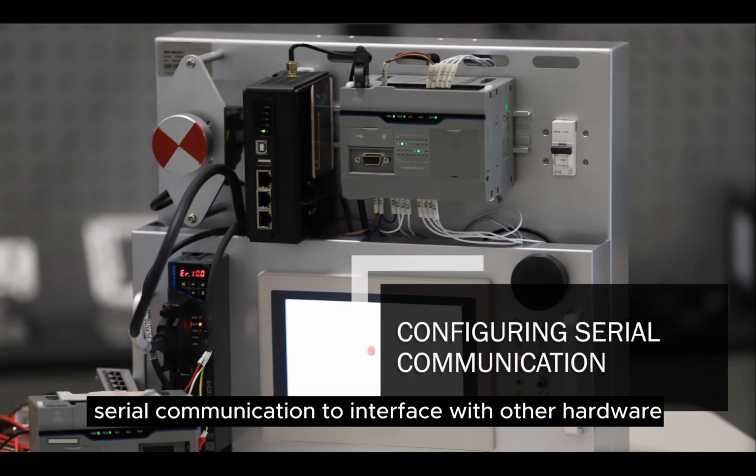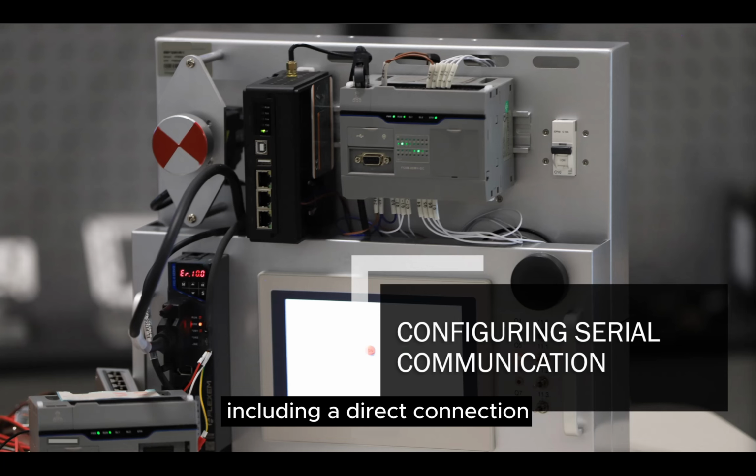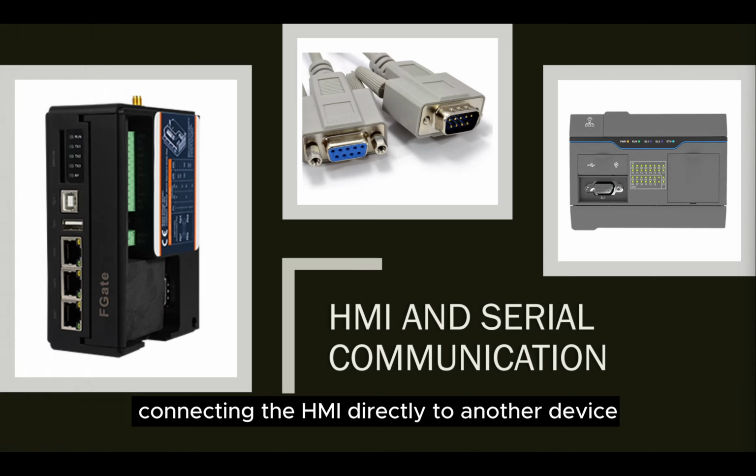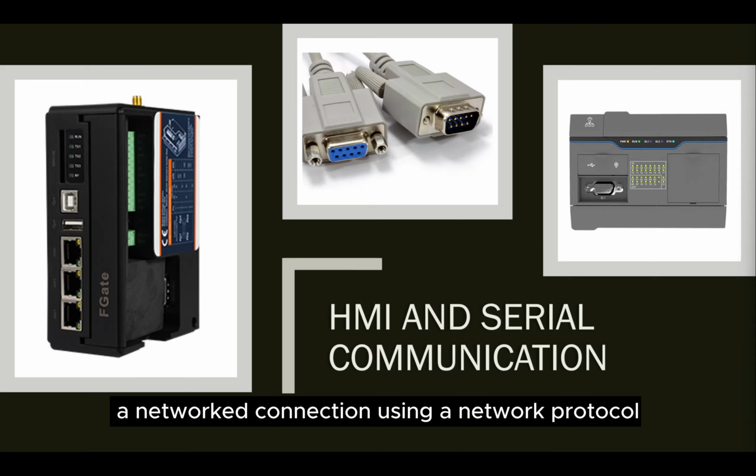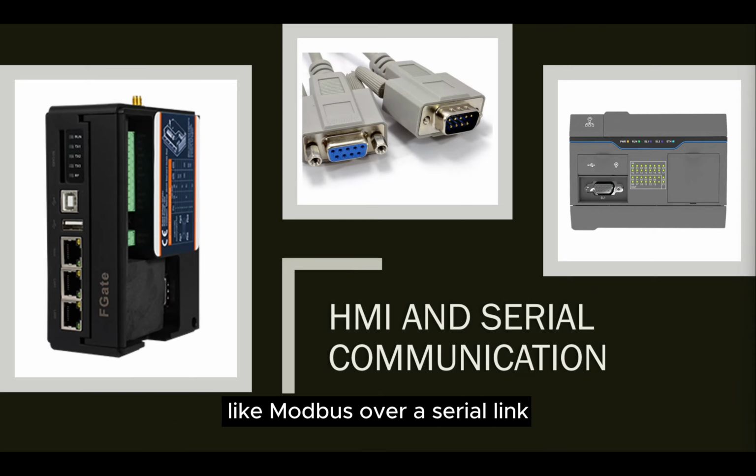HMIs often use serial communication to interface with other hardware. The communication can be set up using various methods, including direct connection, connecting the HMI directly to another device via serial ports; networked connection, using a network protocol like Modbus over a serial link;